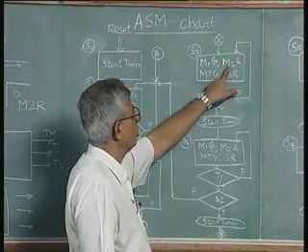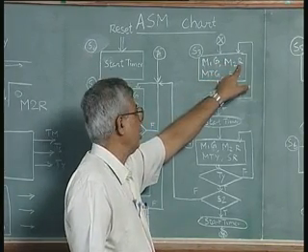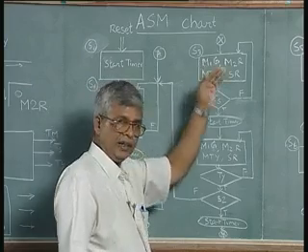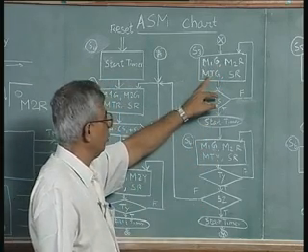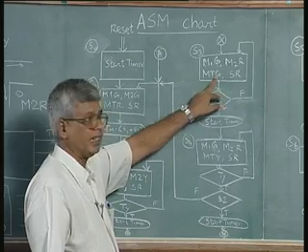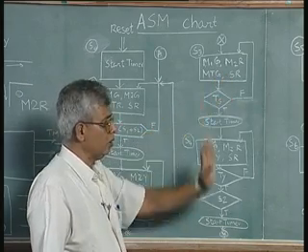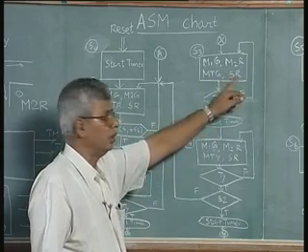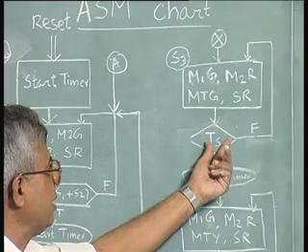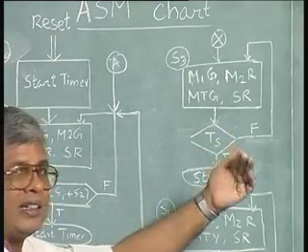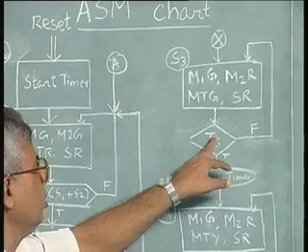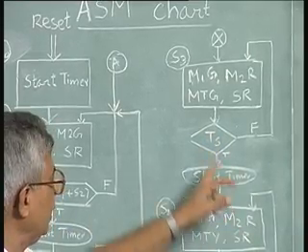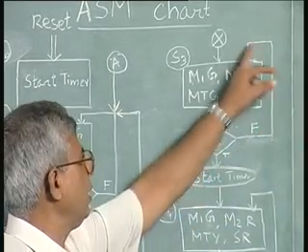main 2 becomes red now, from yellow it has become red, that means the turn from main to right, the turn from main to side, is allowed with a green signal, side to main is not allowed, it is red. Again this period is the duration for which we want the side light to be on, TS stands for the side road light duration, and as long as it is not over it will continue in this state.